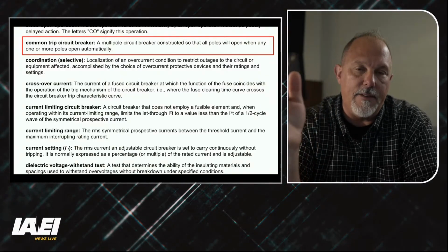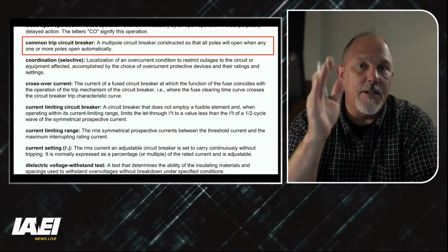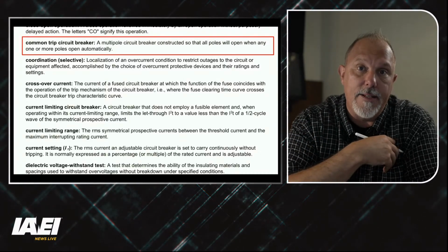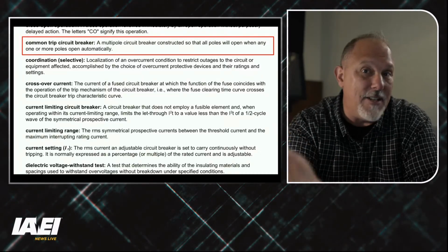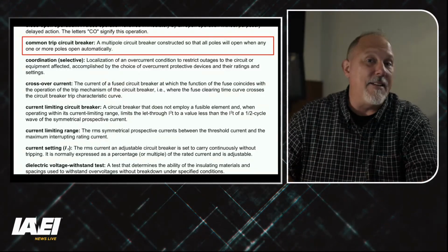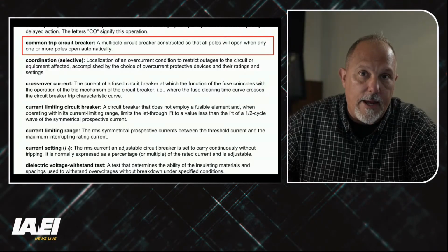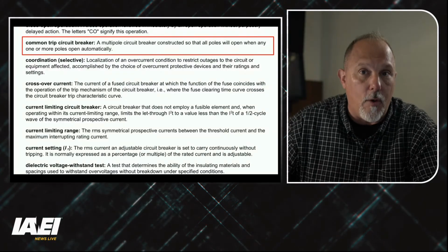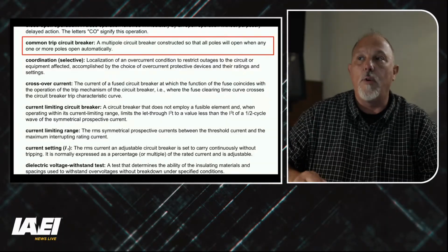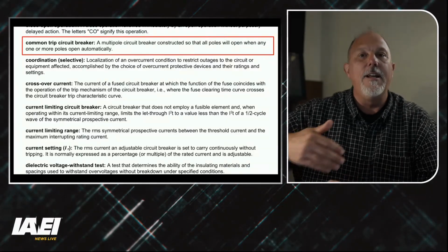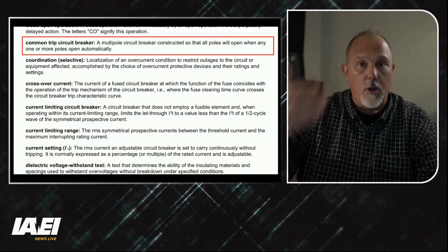Because that fuse is going to be doing the job and it's going to pick up. What I like about that is it gives you an indication. And Jason, you know about this from a 70E perspective. I know IBEW and the Electrical Training Alliance educates on OSHA requirements. You've got to understand what type of fault was out there before you close it back in again.